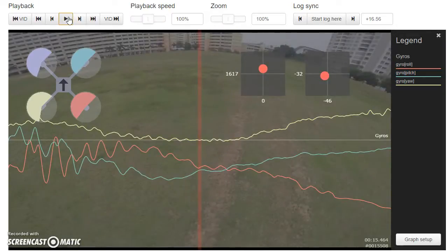And I want to reiterate here, listening to the motors is one of the best ways to find these oscillations. If your motors sound smooth, then you may still be a little overtuned. There's a gray area where you're getting small oscillations that may show up in the camera, but you may not be able to quite hear them, but you can see them in Blackbox. And then there's a point where you cross the line into definitely overtuned, and you can start hearing it in the motors. I say definitely overtuned, but some people like a really sharply tuned copter, and if you do, and you want to accept some prop wash oscillation, obviously that's fine, that's your call.